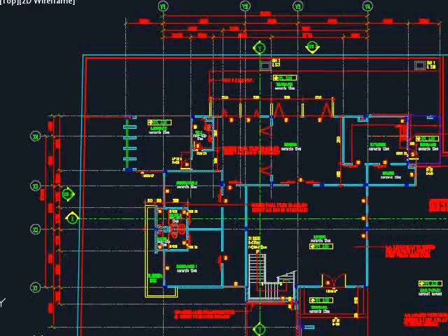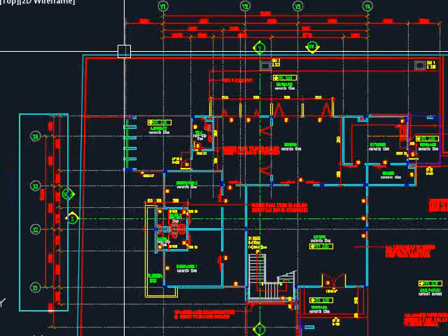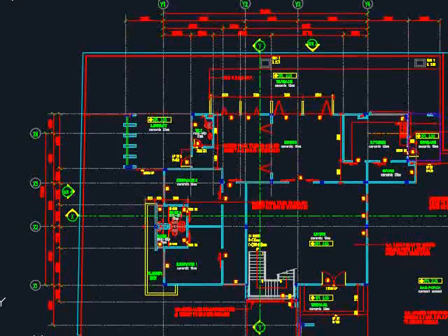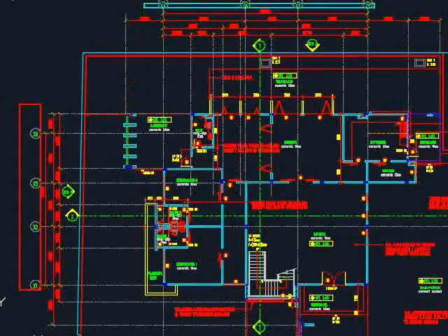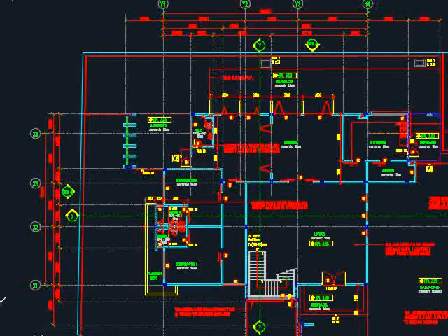The bottom line here is that your gridline system should be more or less similar to the architectural drawing, as the contractor is going to refer to both your structural key plan as well as the architectural floor plan. They need to cover both the structural part as well as the aesthetic part. If you have a totally different gridline system, this will lead to confusion for the contractor, and this is going to cause them a lot of trouble for the purpose of referencing.